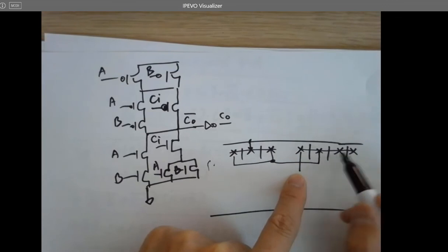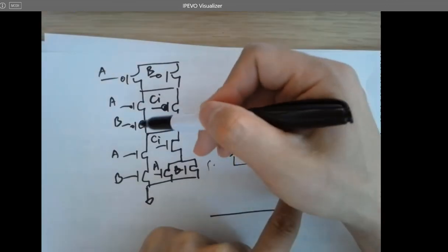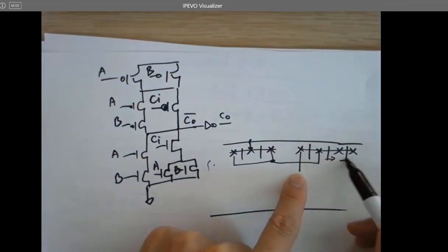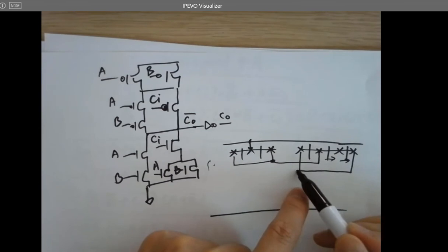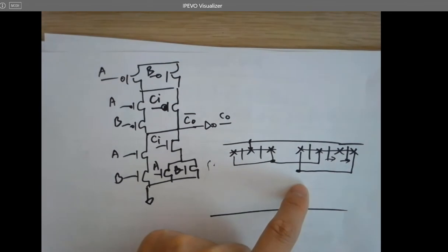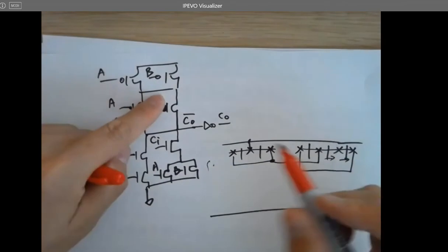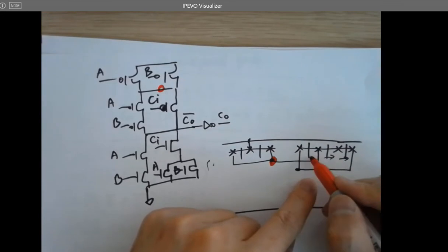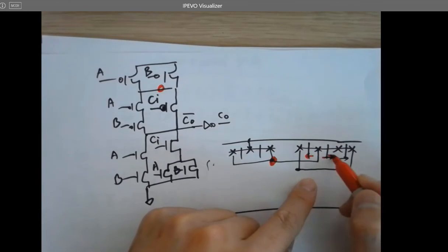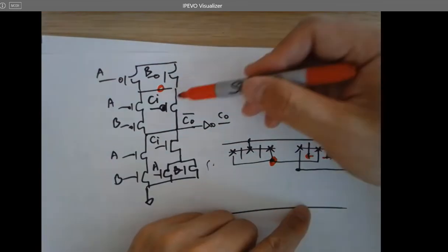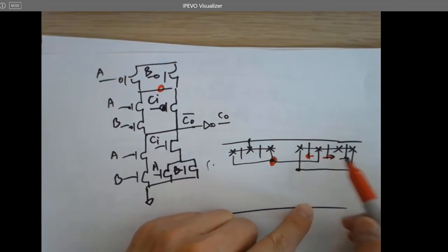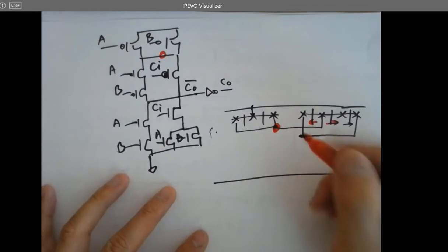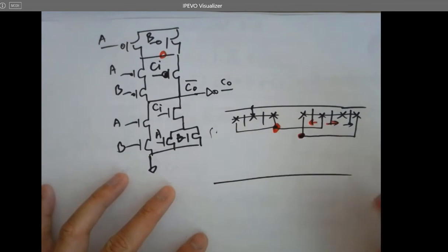Series, actually. These 2 PMOSes are in series. So directly run it through it and then merge as this node. Okay. So introduce that wire, introduce that signal to here, and then 1 branch, 2 branch. So the first branch runs through this single PMOS, and the other branch runs through 2 PMOSes in series. So you can merge the signal out here. That's the output.